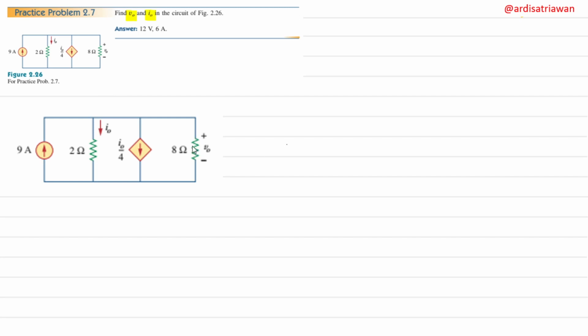So we have this circuit here, and I think this circuit is a perfect example for using KCL. When we are using KCL, the first thing you need is to set your ground. You can pick any node as your reference voltage. So let's choose the bottommost node as our reference voltage, and this reference voltage will equal 0. Because this is V0 from the ground, this node will have the value of V0 with respect to ground. And because all the elements are in parallel, the voltage will be the same.